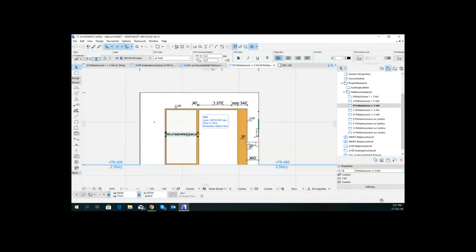But if later on down the track she decides that that window becomes clear or blue glass or red glass or whatever, she has to then come back and find this window, remember that it's there, and change it. Because that is just a standard old piece of text that relates to nothing.